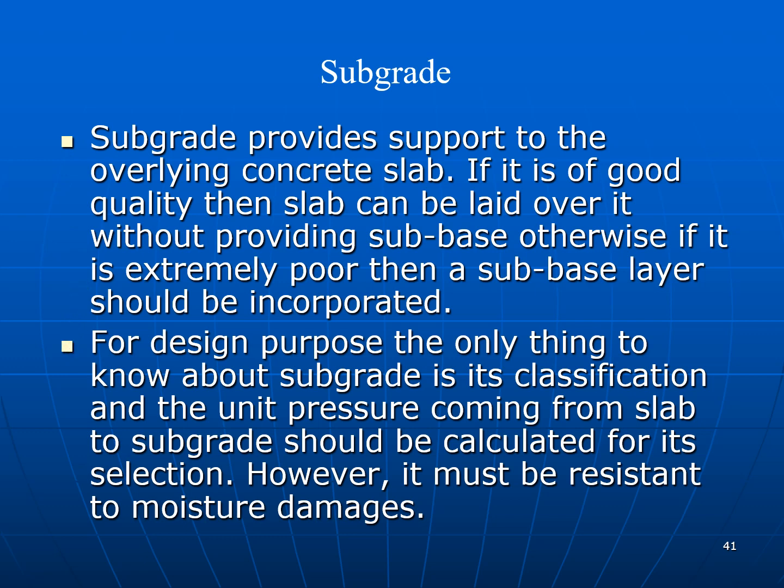For design purposes, the only thing to know about the subgrade is its classification, and the unit pressure coming from the slab to the subgrade should be calculated for its selection. However, it must be resistant to moisture damages.